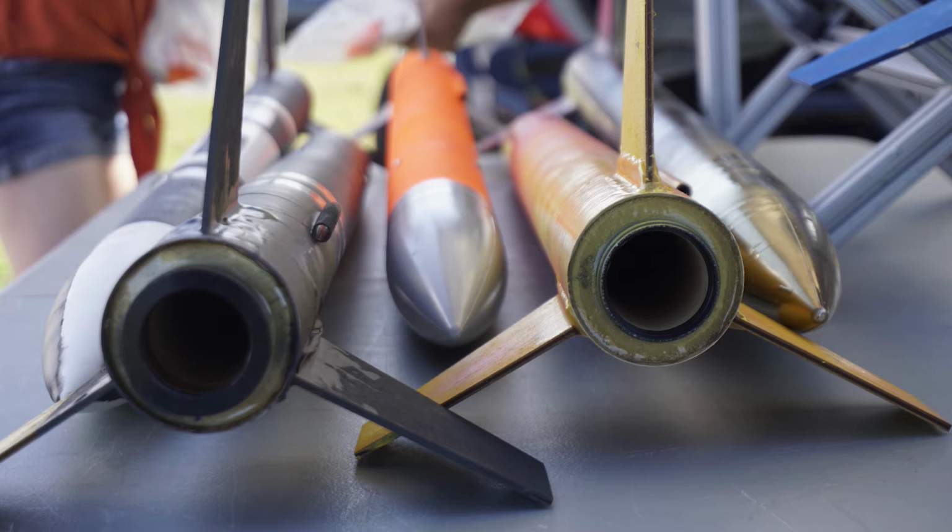The center of mass of a rocket is easily found through simple methods. However, the center of pressure is optimally found through the use of a wind tunnel, which was not available to use. The center of pressure can be approximated in a more rudimentary experiment. It is known that the caliber of stability, which involves the distance between the center of pressure and center of mass, is acceptable for a successful flight.